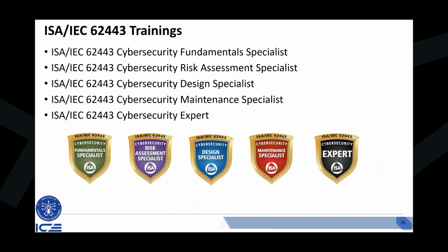What is the minimum level in Purdue model I can apply data firewalling on? There is no requirement. Like I said earlier, Purdue model doesn't have any direct correlation to cybersecurity, so you don't have to apply a firewall at all. But if you want to, you can apply it at any level. You can put a firewall in front of the PLC itself. So there's no restriction as to where the firewall can and cannot be installed. You can put 1,000 firewalls on every device if you need to.